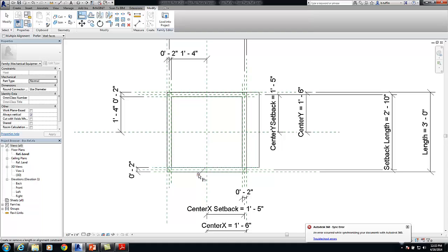I'm literally not drawing that masking region on a floor. I'm drawing it on the plane. So if I created a top plane, which I do have here, I could set that plane active and start sketching on that plane. So yes, you definitely can.